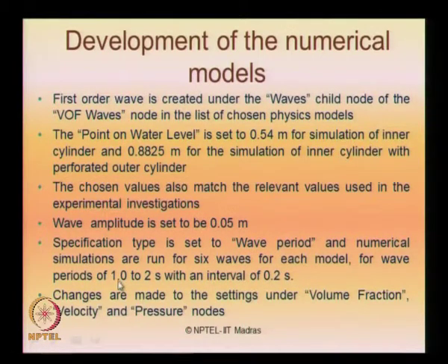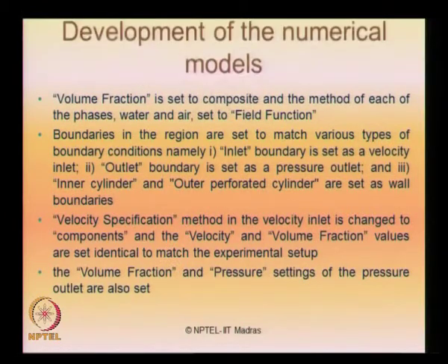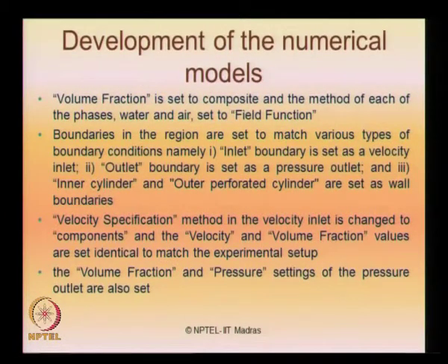The specification type used is wave period, and the numerical simulations are run for 6 waves of each model, with wave periods varying from 1 to 2 seconds at an interval of 0.2 seconds. The changes are made for the settings under the volume fraction, velocity and pressure nodes. The volume fraction is set to composite, and the method of each phase, water and air, is set to fluid function. The boundaries in the region are set to match various types of boundary conditions.